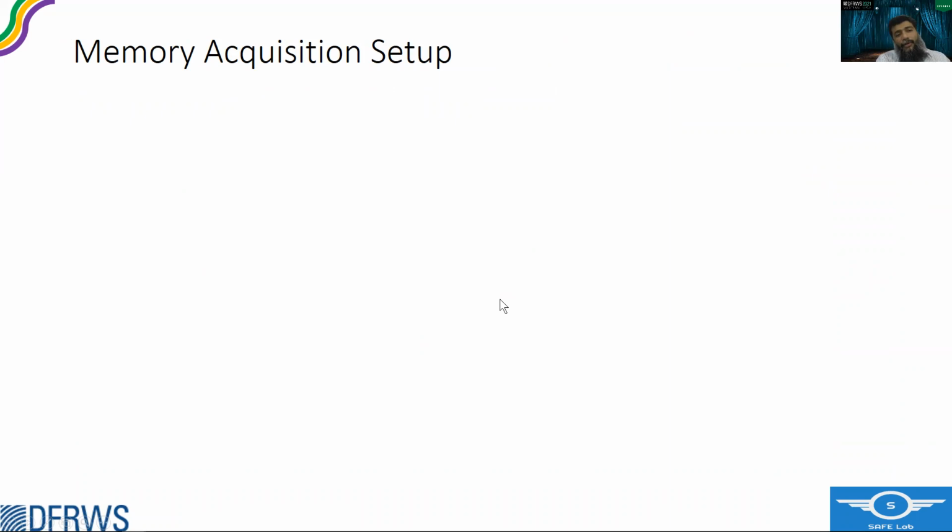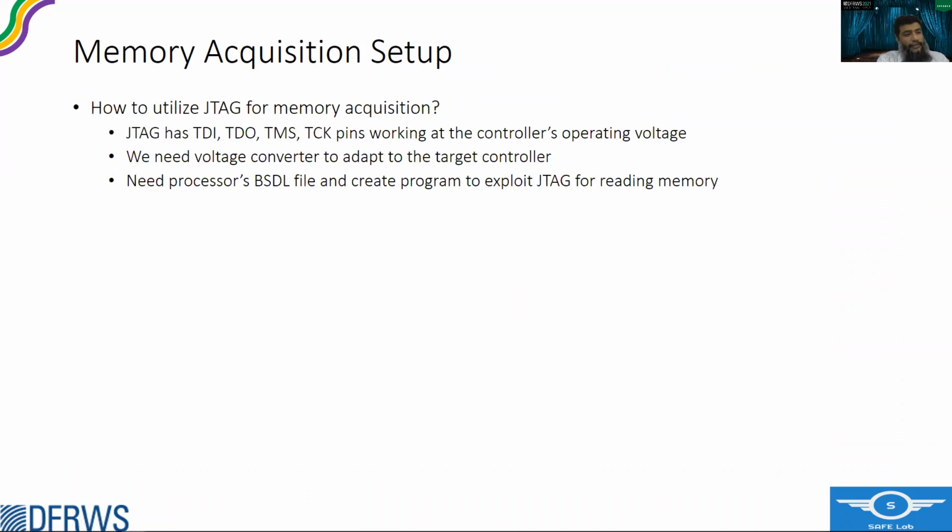The next step is the memory acquisition setup. So once we find the JTAG pins, how do we use the JTAG for memory acquisition? JTAG has a few pinouts, and these pins work at the controller's operating voltages. So we would require some voltage converters, then we would also require some BSDL files, and then create programs to exploit JTAG for reading memory.